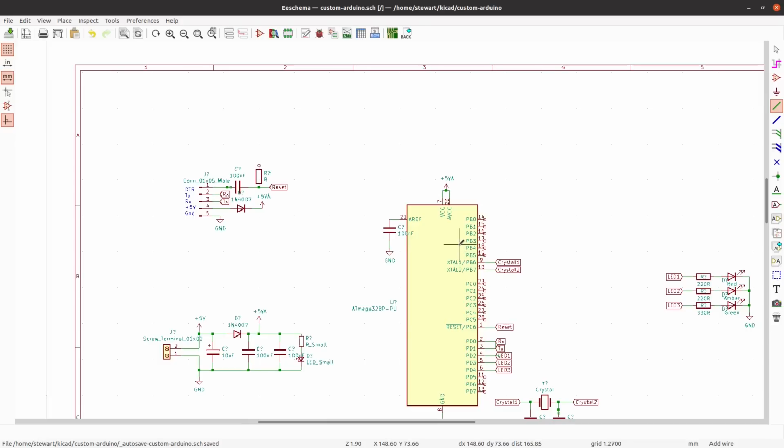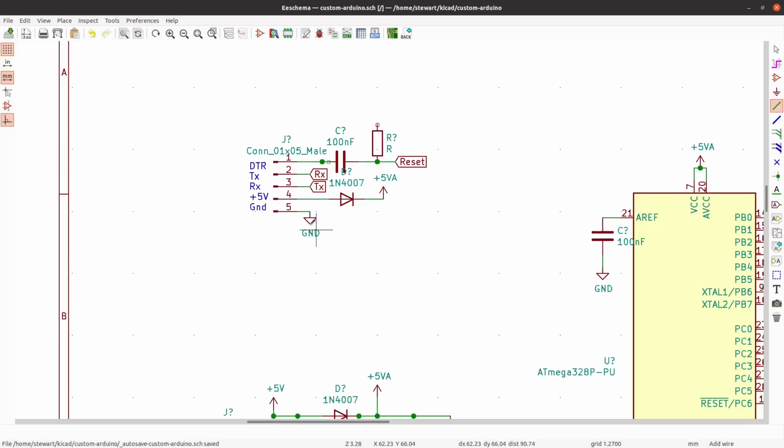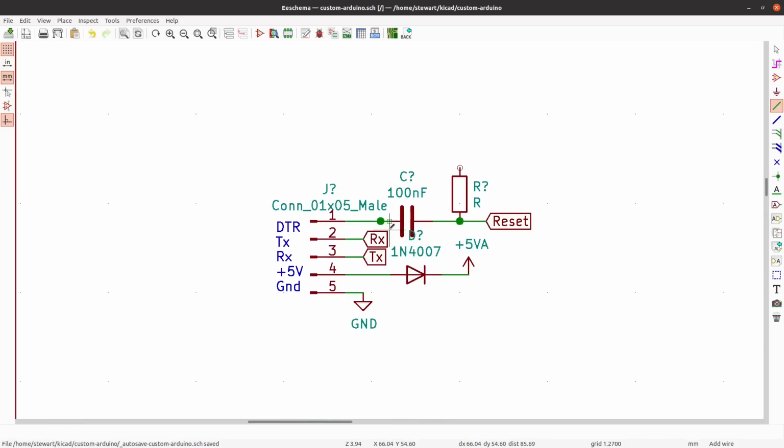Now I can just have a quick look around the diagram, make sure it's everything I wanted. That looks like it. So the circles denote wires crossing. If you've got two wires that are connected directly, you don't normally get a circle, and if you've got two wires that cross at right angles that don't connect, then you don't get a dot. So I'm guessing that looks like I've overstretched a little bit, so I'll just delete that. Horizontal wire, oh there we go, that looks better.